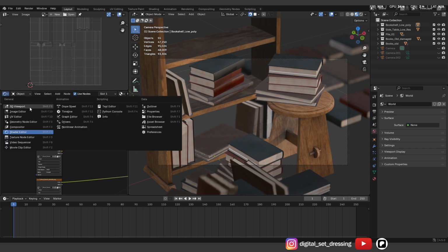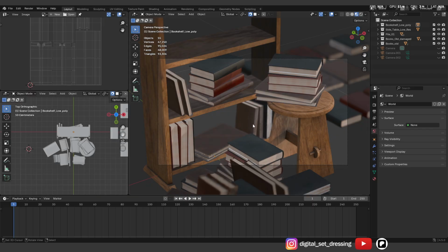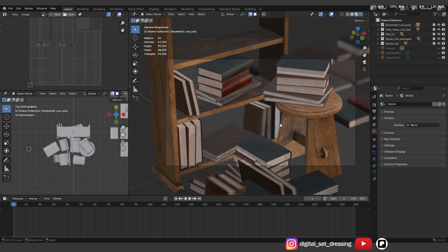Over here, I can create a 3D view and then come into the top view. The reason we're creating 2 spotlights is that I can use one spotlight to create a very hard beam and then use a cookie cutter stencil on that beam to create shadows from outside, as if the sun is coming through a tree or leaves. And the second spotlight is fill, but it is directional fill. It's not like an HDRI that has a global fill. So let's go ahead and set that up.